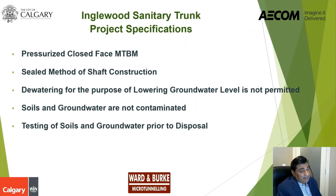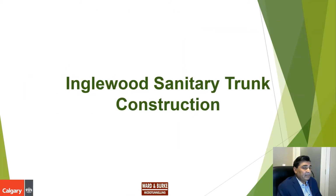Because if we do dewatering, first of all, it is not practical, but even if it is practical, there is potential that because of excessive dewatering, there will be impacts on adjacent infrastructure, and we don't want to do that. And then we said soil and groundwater are not contaminated. However, testing of soils and groundwater is required prior to disposal. Then we will see what we encountered during construction.